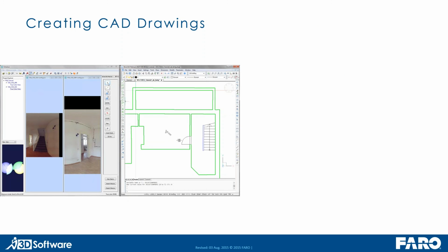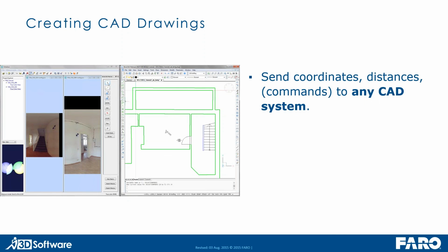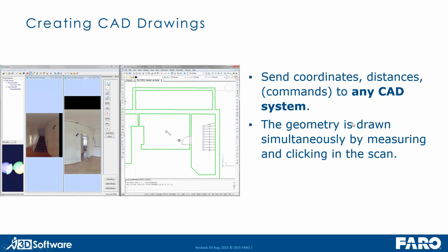If you are interested in CAD drawings as a result, you can create those using VirtuSurv, and it works in a way that you send coordinates and distances, and if you have a CAD system where we have a direct link like BricsCAD or AutoCAD LT, you can even send commands to your CAD system. But coordinates and distances you can send to any CAD system.